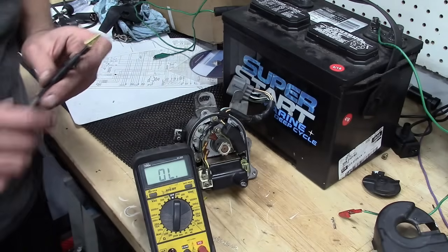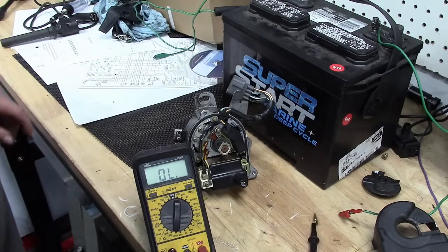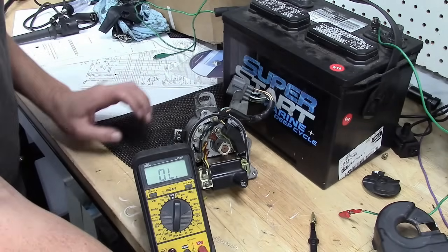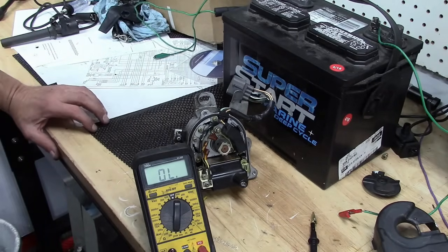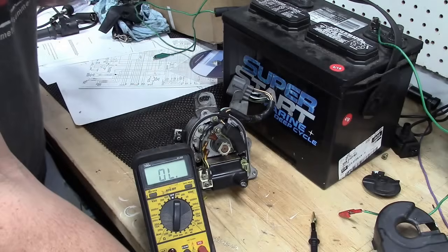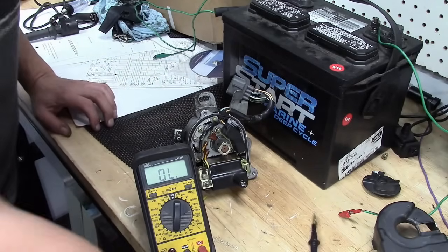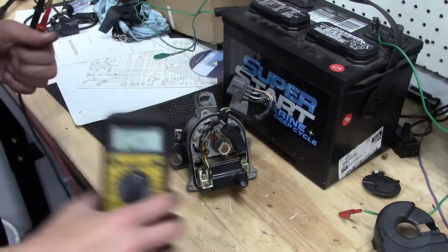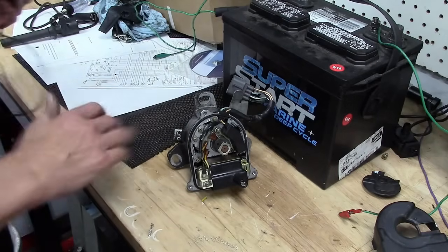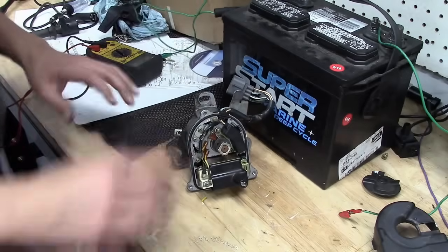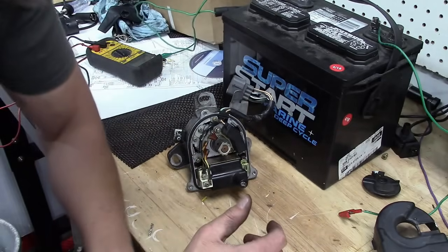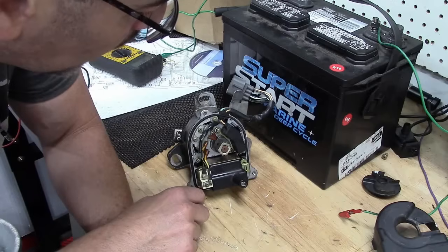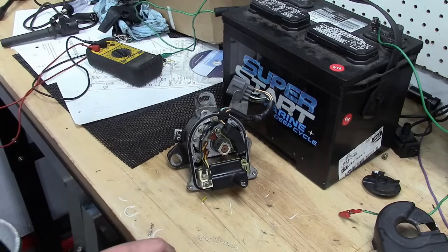There is a spec you can look up. Honestly, I'd never bother with that. I don't like doing resistance tests to validate a part. I only like it under load when it's performing. So I am only going to believe a spark test on this. At this point, we've got every indication that there's no wiring problem with this distributor that we suspect so far. What we want to do is fire this coil.